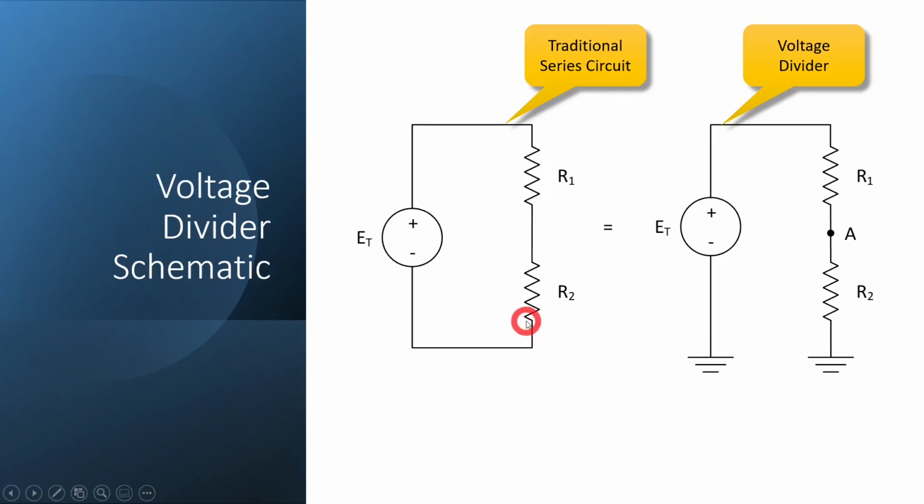This circuit here has a common point electrically through this wire that comes over to the negative of our power source. Here we have two grounds. Whenever you have a ground symbol, they all are referencing the same point electrically. So that means that these two are the same point electrically. So therefore, we could actually draw a line between here.